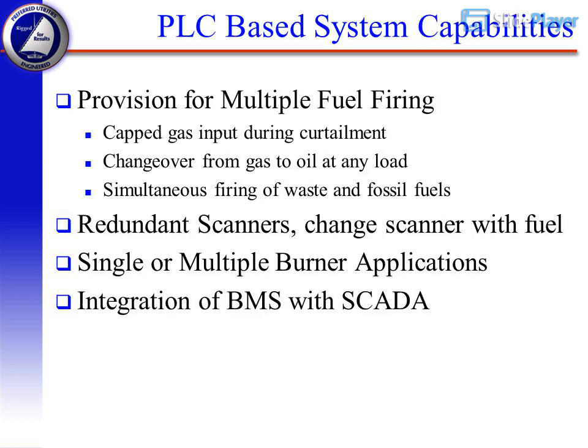PLC-based system capabilities. Provision for multiple fuel firing. Capped gas input during curtailment. Changeover from gas to oil at any load. Simultaneous firing of waste and fossil fuels. Redundant scanners, changing scanner with fuel. Single or multiple burner applications. Integration of BMS with SCADA.